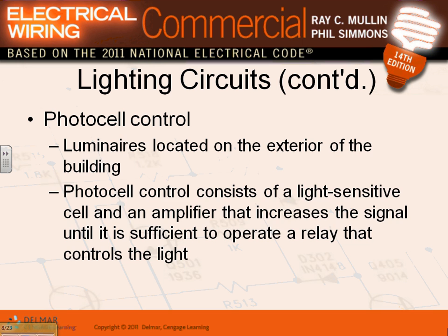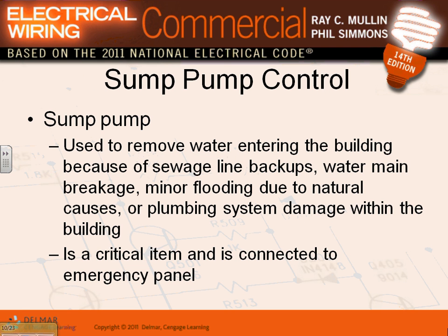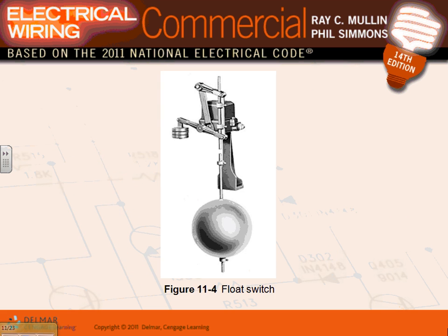Photocell. I'll talk about the exit signs. We talked about exit signs, guys. You have installed them. Exit signs have a battery on them. You always power the exit signs from the circuit that feeds that particular area, from the line side of the switch, not the load side. And you guys have done it with me, no switching for them. We'll talk about the sump pump and the circulation in a second.